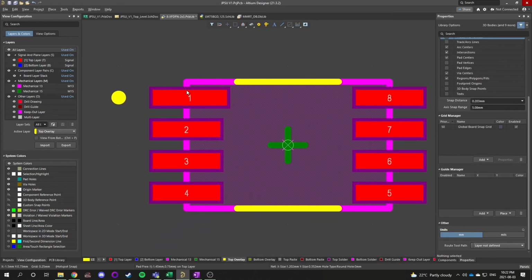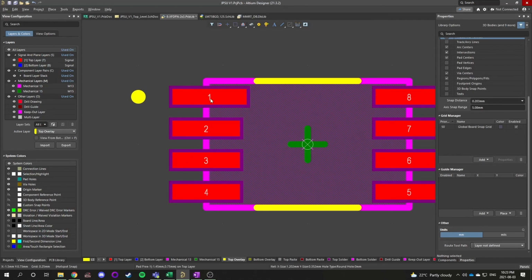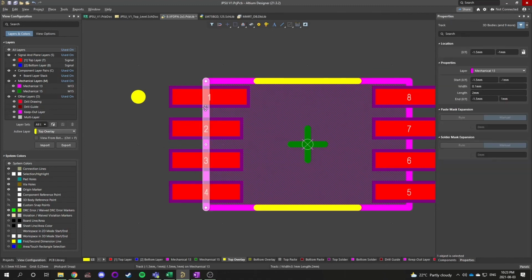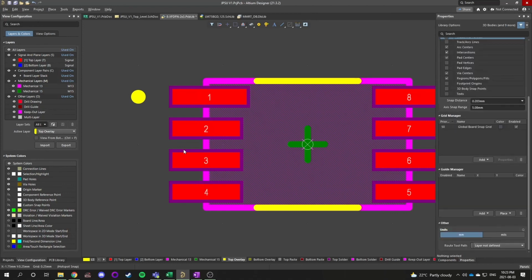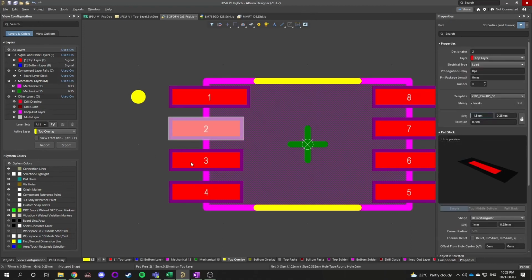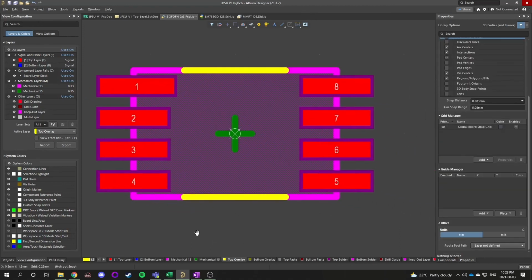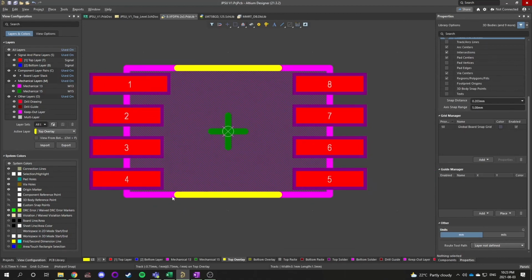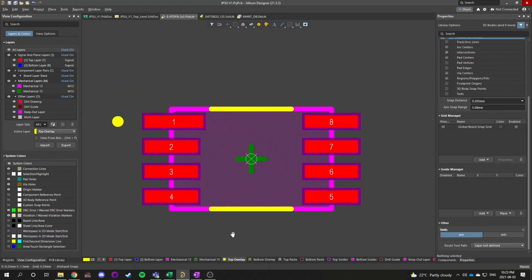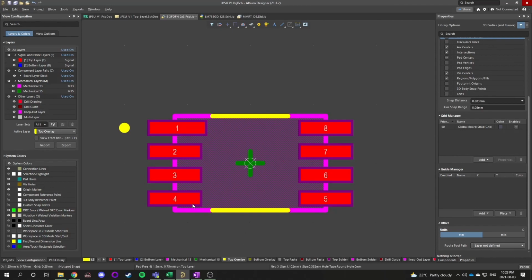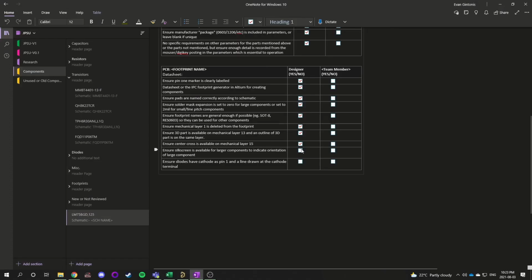So for the smaller or shorter edge of the package, the pads actually stick out further than the package edge, so we know that we physically can't place components that'll intersect with this edge of the package because it'll intersect with the pads, but we already know those are there when we're doing our routing. It's just this little lip here you gotta be worried about. So things like that, make sure you're compensating for. So that means that's checked off.